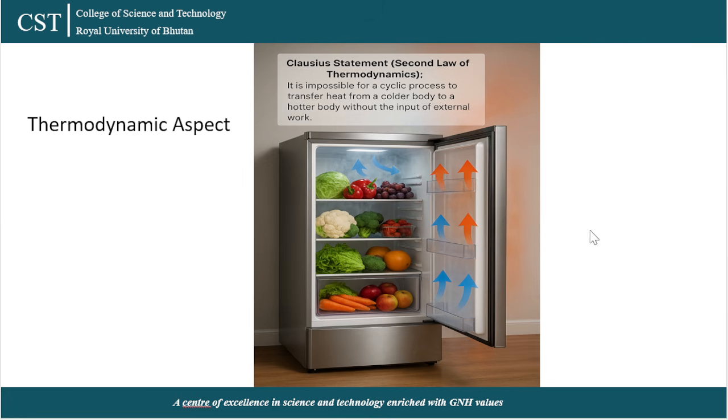So that means this is not going to be a spontaneous process. This is going to be a non-spontaneous process. You are trying to extract heat from the colder region and dump the heat into the hotter region. So at first, this may seem like it violates the second law of thermodynamics, but it doesn't. If you clearly see the definition of the second law of thermodynamics, the heat transfer is possible because we supply external work in this case.